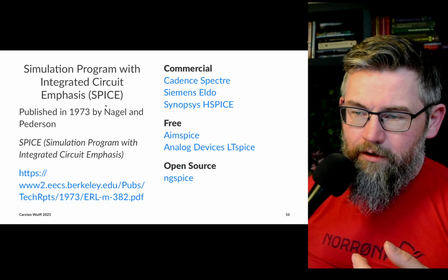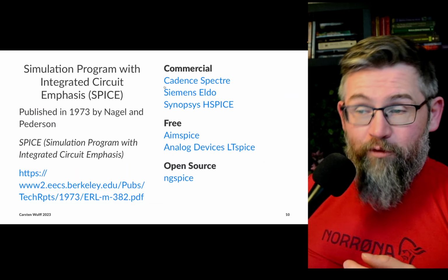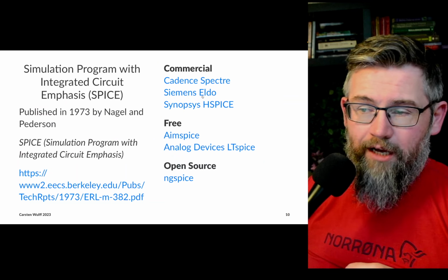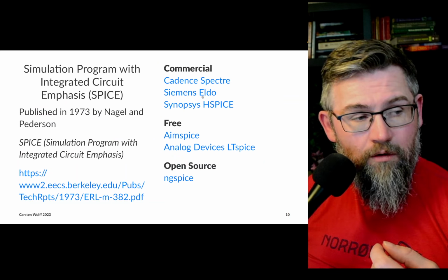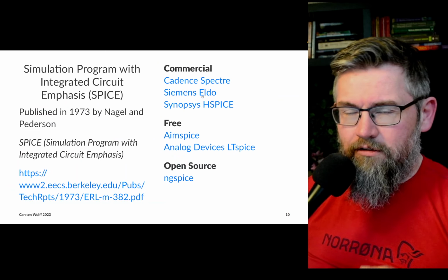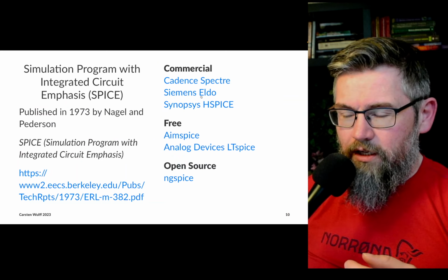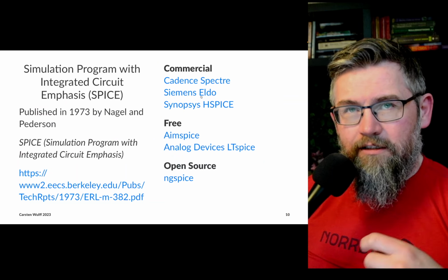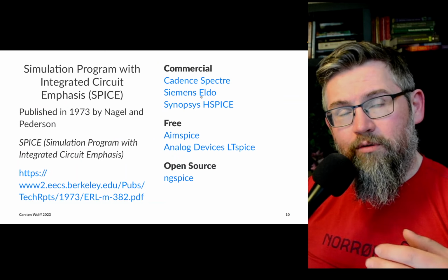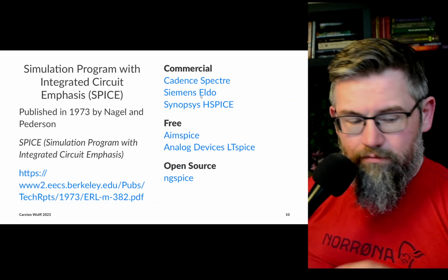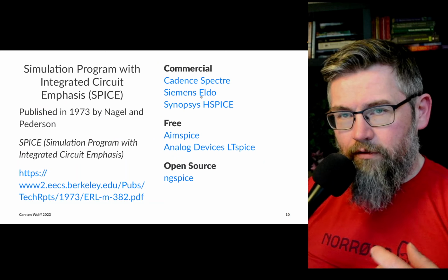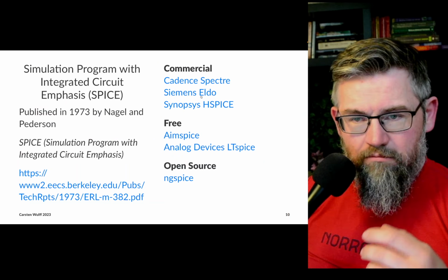But for SPICE simulation, you also have commercial tools. I would say that for analog design, Cadence Spectre is dominant, but also Eldo was pretty good. You have fast SPICEs like AFS and what's it called? Maybe it's not called Berkeley SPICE still. Well, at certain points in time, there will be faster SPICE engines. And one of the key things when you're trying to figure out the next state in this horrible equation of nodes is how long a time step you can take, because the time step that you take to compute the next value depends on the derivatives of change in voltage and current and all that stuff. So some simulators try to be a bit more creative, which is why we get fast SPICE, but anyway, all of them are slow.